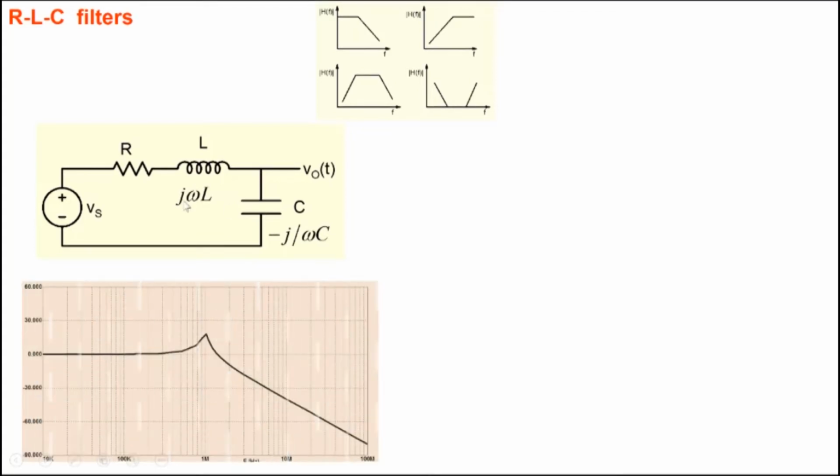So in this case, if we look at this circuit here, if we take the voltage across the capacitor, you can verify that this acts like a low pass filter. It passes the lower frequency and then higher frequencies it rejects, and interesting things happen around the resonant frequency part here.